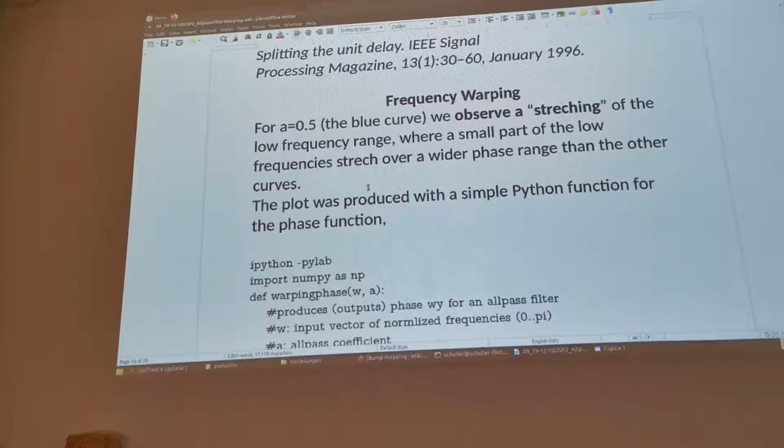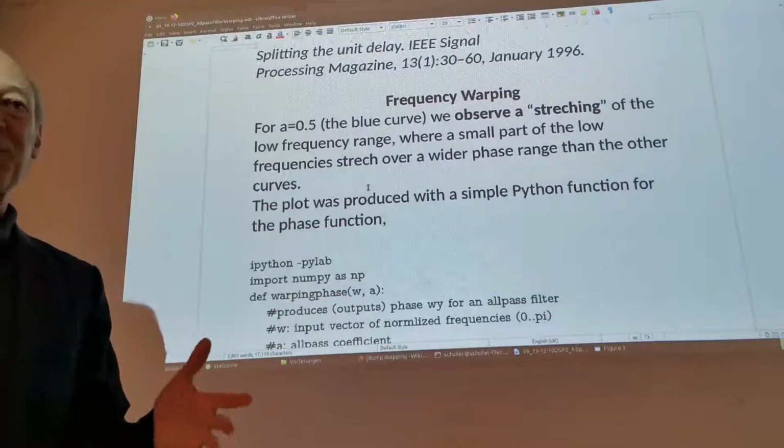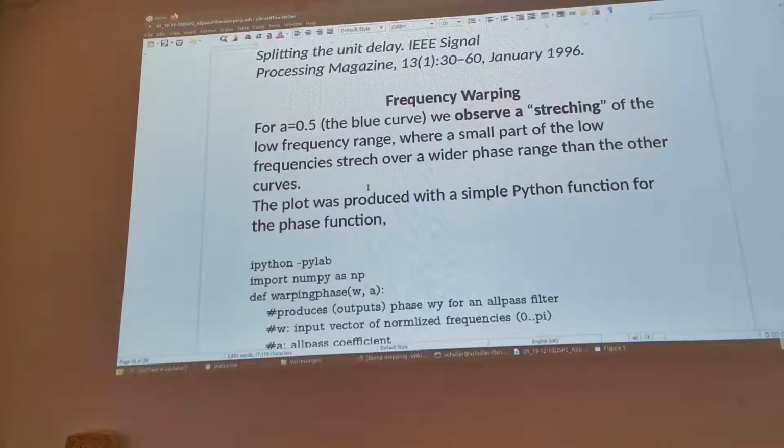So that is the phase we are remapping as phi equals 2 pi f d. Normalized frequency is 2 pi f divided by fs, so pi would be the Nyquist frequency. We basically interpret the phase, which in this case goes from 0 to minus pi, as a frequency. Remember, the phase doesn't have to stop at minus pi.